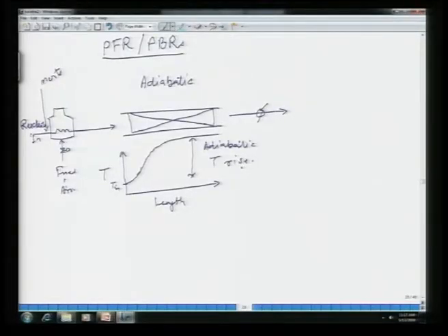For example, I don't know the example. So, you would like that the inerts or the non-reactive components in the feed stream be increased. What that will do is, the large presence of inerts gives you a capacity to absorb heat. Per unit volume of the reactor, less heat will be released, because most of that volume is occupied by the inerts, and because the inert forms the major fraction of all the components, it does not participate in the reaction.